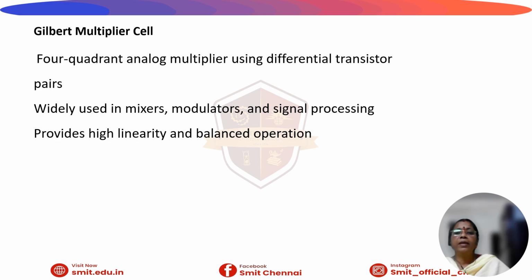It is a four-quadrant multiplier which uses differential transistor pairs. It is widely used in mixers, modulators, and signal processing. It provides high linearity and balanced operation. It is a foundational analog circuit that multiplies two input signals to produce an output proportional to their product.